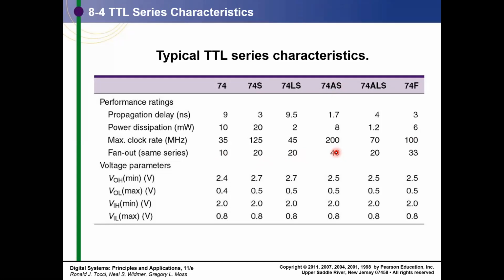So you can even see the 4 voltages. These 4 voltages are known as the critical voltages, which determine your noise margin. So you can see there are variations. This was the typical which we had talked about, 2.4 and 0.4 on the output side, and on the input side acceptable values 2 and 0.8, which gave the noise margin of 0.4. But if you see over here, the noise margin for high is 0.7, for low it is 0.3.